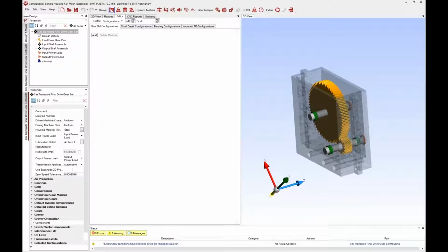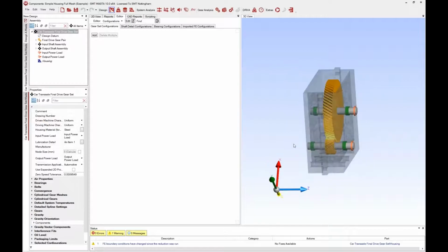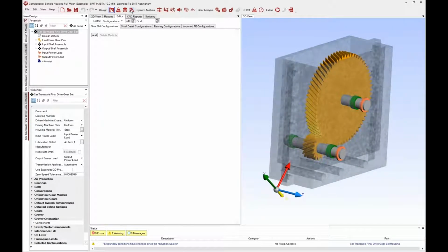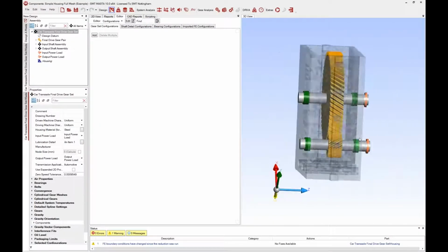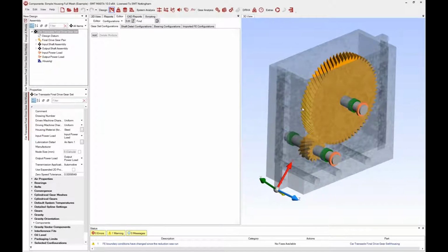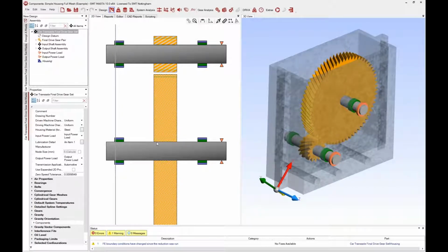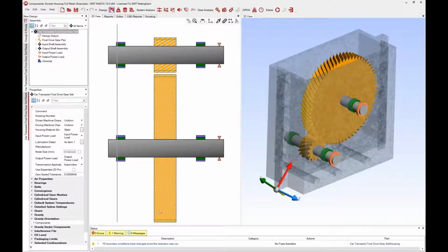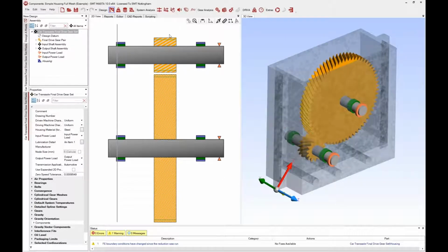Okay, so something that was brought in one of the latest releases, MASTA 9, I think, was the ability to actually mesh a shaft profile. So if you wanted to create an FE model of a gear blank, for example, and it was exactly the same as the MASTA Timoshenko beam was modeled. So let's say, for example, we want to replace this with an FE model, as the Timoshenko beam won't capture the flexible behavior of this blank. We could create a mesh of this particular setup.